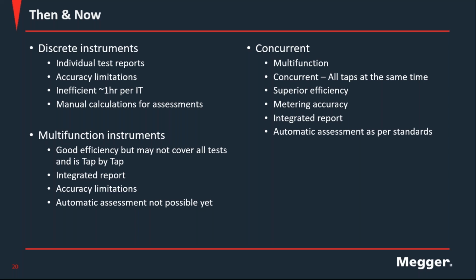You can easily spend 1 hour testing one CT for all the taps because you need to change leads, swap instruments, and open different software. And when you go to test CTs or VTs, you don't have just one. You have many of them, and it will take a lot of time. So it's important to consider a tool that can help you expedite the testing. And even if you do it with discrete instruments, if you want to run the assessments, you will need to run manual calculations using those results from the tests.